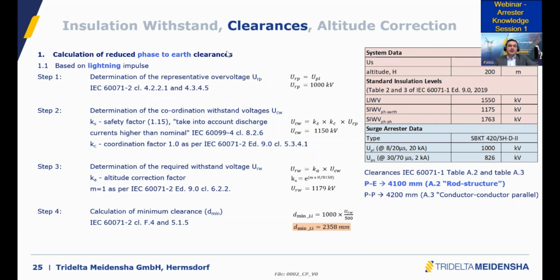So in that case, when you have tested your equipment in the test lab, you have performed a test at sea level, and you have applied an altitude correction factor to guarantee the value as standard for 1,000 meters.